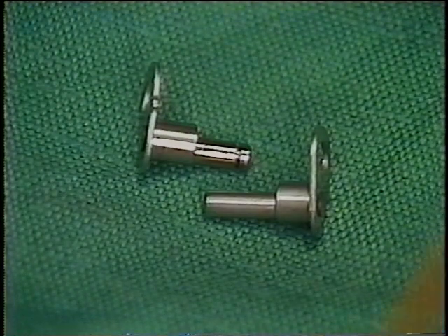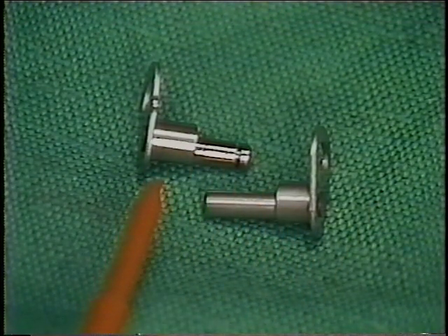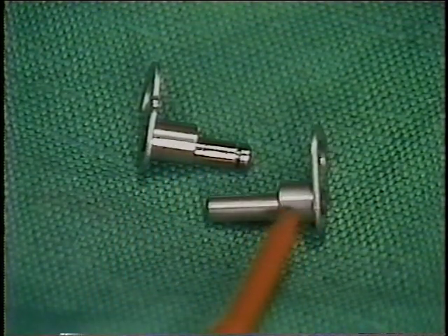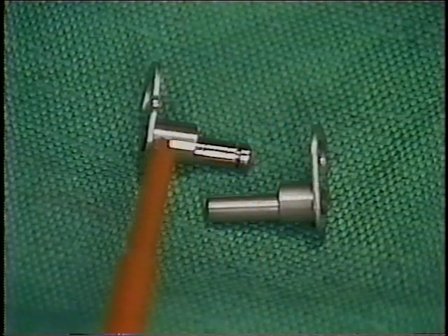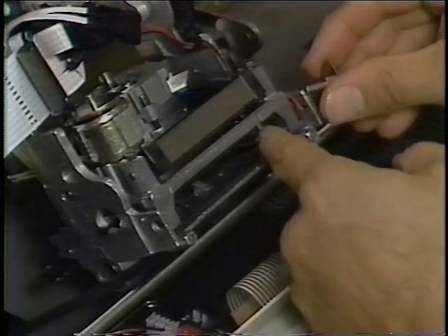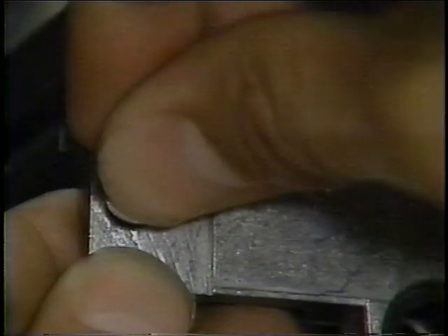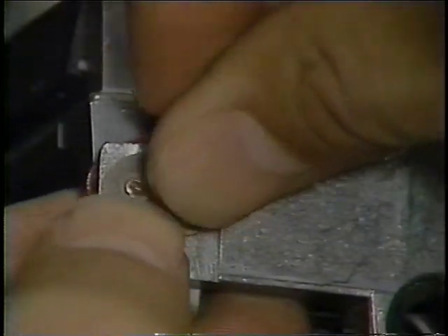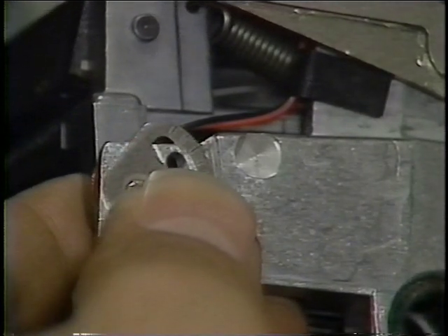These are the selection plate pivot eccentrics. The right pivot eccentric has a narrower shoulder than the left pivot. Remember that these are not interchangeable. Install the right selection plate pivot eccentric. Align the pencil mark with the edge of the carrier casting and tighten the screw.